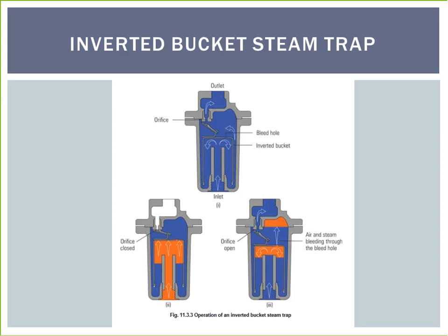In step 2, air reaching the trap at startup will also give the bucket buoyancy and close the valve. The bucket vent hole is essential to allow air to escape into the top of the trap for eventual discharge to the main valve seat. The hole and the pressure differential are small, so the trap is relatively slow at venting air.